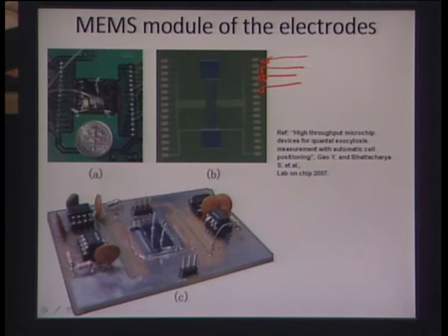So, if you see here, these are screen printed electrodes on a silicon wafer which can be easily fabricated using the microfabrication strategies that we have been talking about before, and there are these small positioning channels, these narrow small positioning channels between these sensing electrodes, and two reservoirs essentially on both sides here,